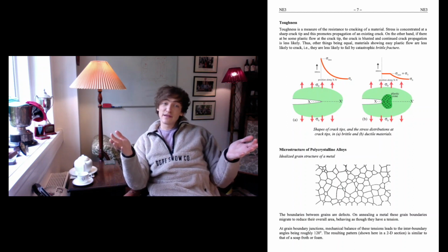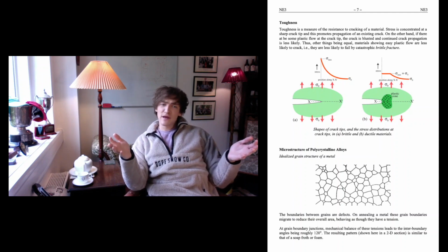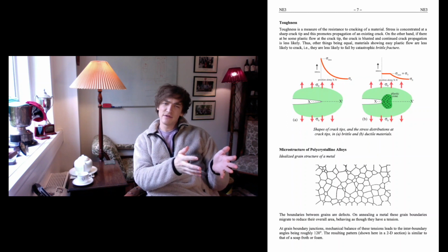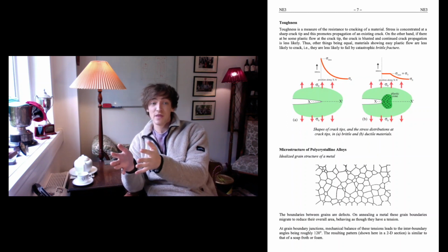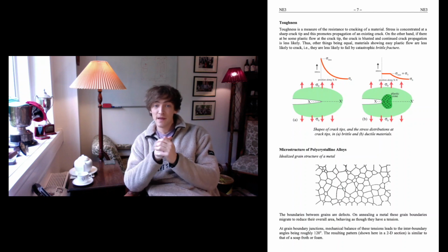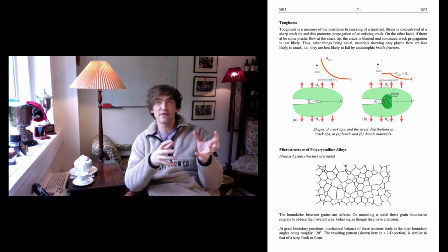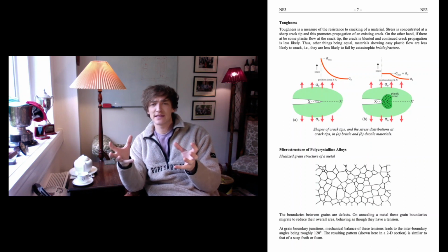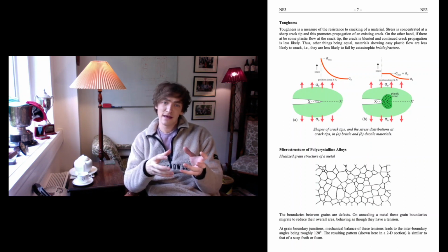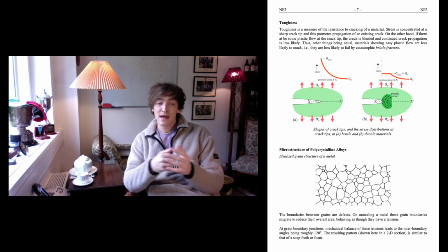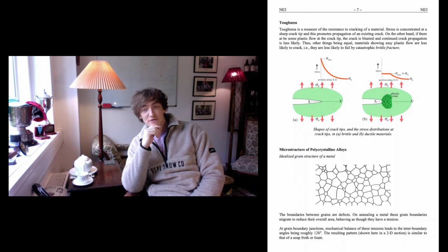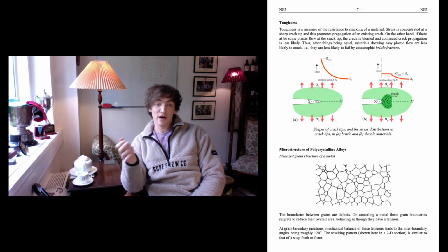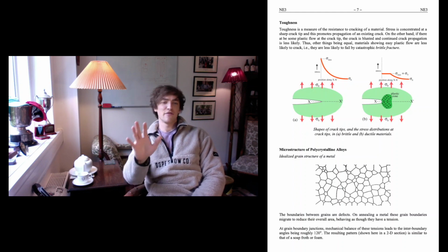So we can think about it in terms of strength. Increasing the strength of a material in most cases will reduce the toughness of said material. Because when you strengthen something, it can take less energy by plastic deformation. And because there's limited plasticity, it's going to be a brittle material. Now there are ways that you can increase both characteristics, notably reducing the grain size of materials, but I'll talk about that later. I don't want to overwhelm you.